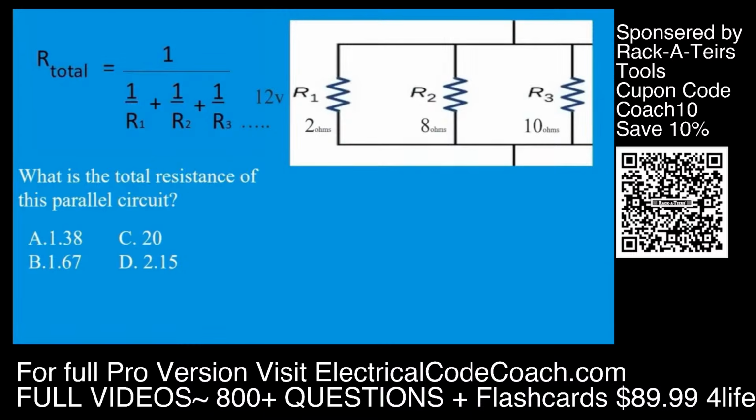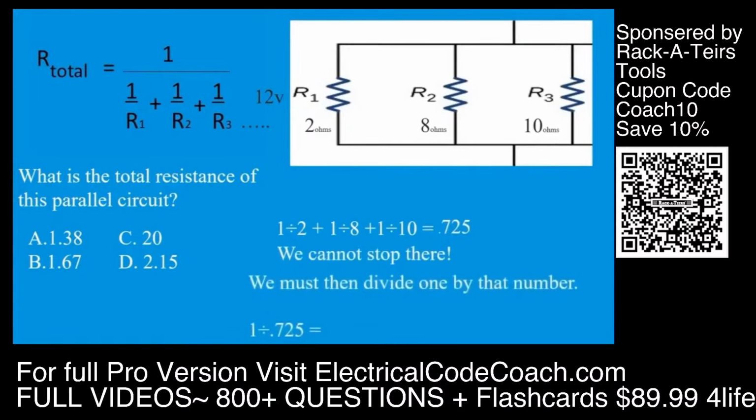So let's move forward. We take 1 divided by 2 plus 1 divided by 8 plus 1 divided by 10. We cannot stop there. We must then divide 1 by that number. That is going to give us 1 divided by 0.75, and that is going to give us 1.3793. We're just going to round up to 1.38.